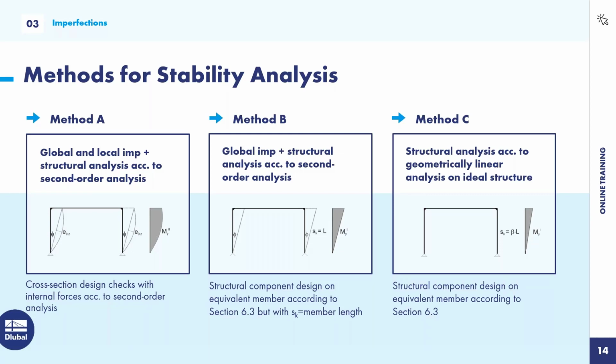But you have to consider, and that's quite important, for the design of lateral torsional buckling, the application of the second order analysis is also required with this method.